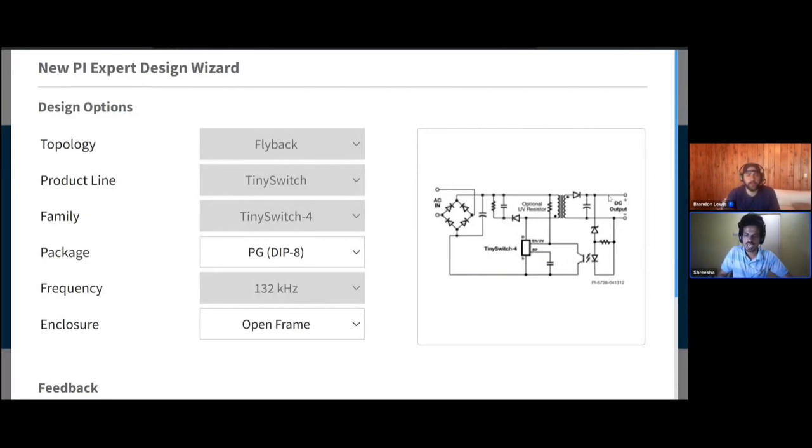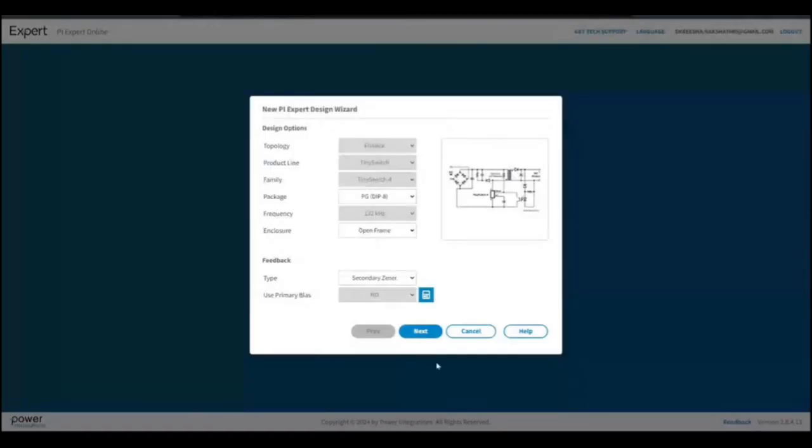So in the application, when the load changes, the voltage changes here as well, it will drop or it will spike up. At that time you need feedback to correct the power on the output. That is why you have this optocoupler here. So this forms the feedback circuit. So this is a simplified circuit diagram. We can just select next here.